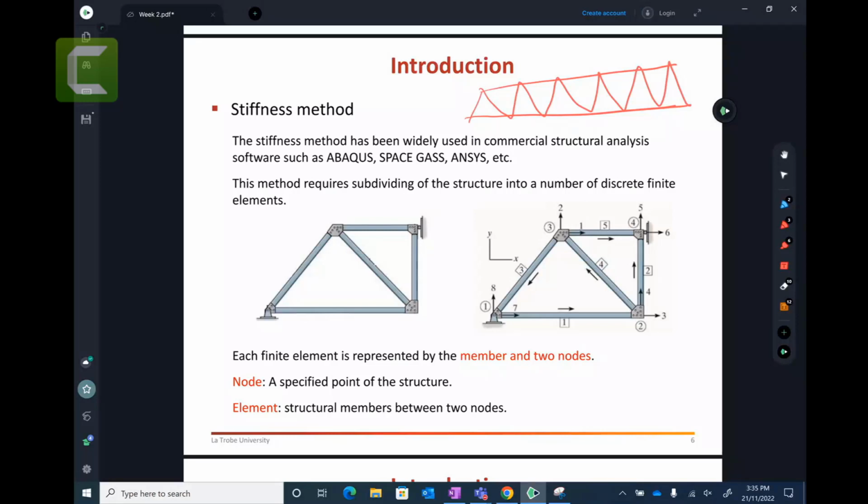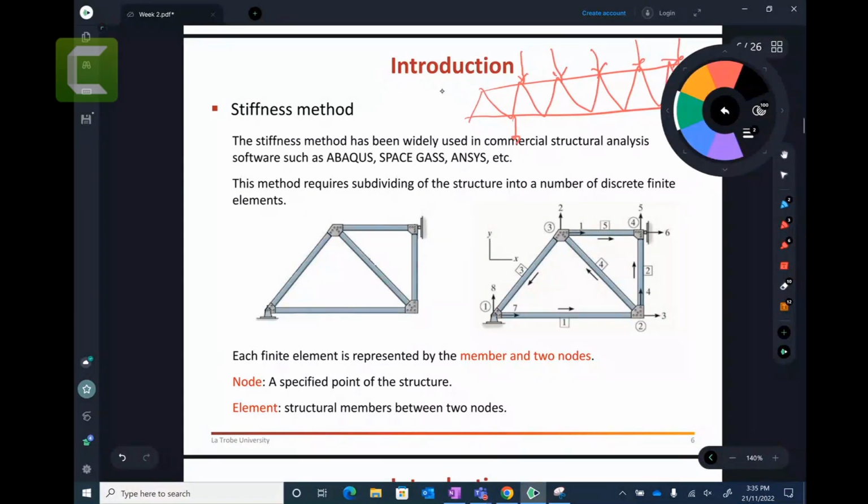The main philosophy of the truss is that the loads are only applied to the joints. You can see the loads, and you will never get these ones. You will never ever get these ones. No, that is wrong. The truss will not get any load coming onto the members, right? So that green one is wrong. They will not have any. The beauty of this truss is that the loads are only acting at the joints, which is a good part. That is the one philosophy.